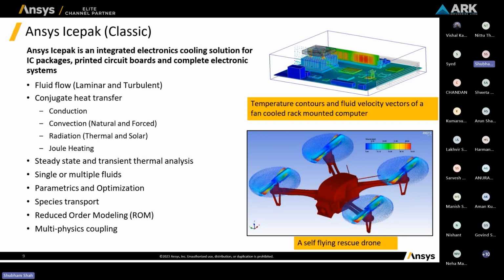When it comes to a combination of fluids, it is suggested to go with the species transport model. In that model, we will add two materials, and we will give the quantity and define it, like 50% glycol and the other 50% will be water. And this is how we can use a species transport model.